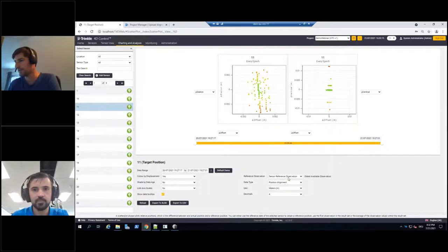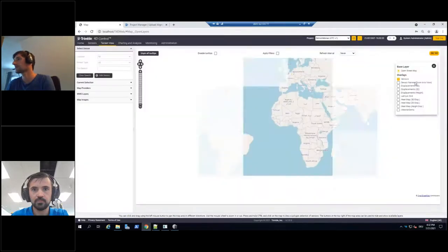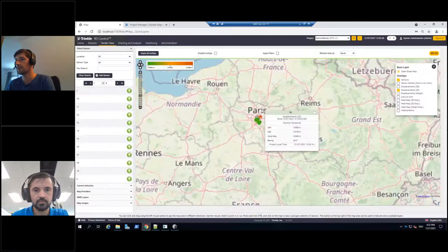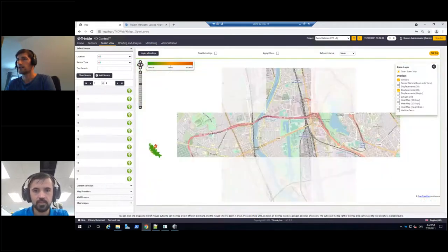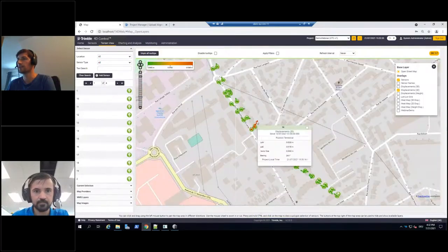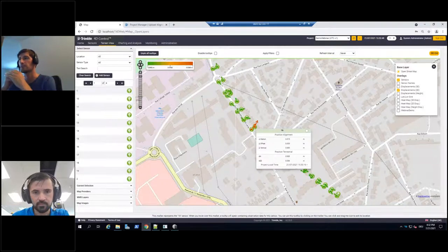So this is not, you can see I can go back maybe to the maps page. So here, let me enable this again. And if I go back, I think this is what Julian meant. So if you look here, it shows the vector size, but again, this is based on the northing and easting values related to your coordinate system. So this is not derived from the alignment-based information, but you can see the alignment-based information if you click on the sensor icon itself.